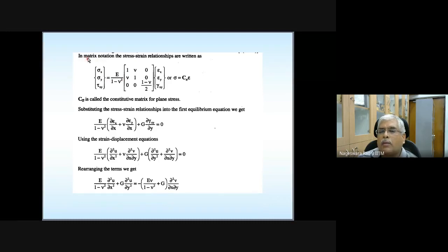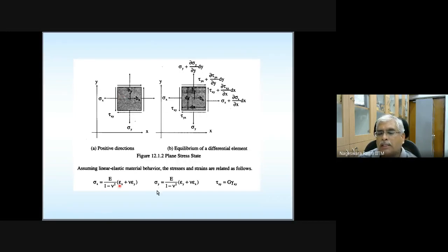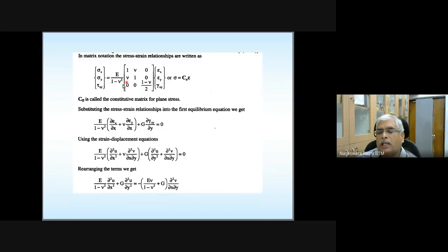These are the stress components, these are the strain components, these are the stress components which are not zero, corresponding strain components, and how they are related coming from these relations. And this 3x3 constitutive relation can be compactly written like this. And this matrix is nothing but your constitutive matrix. Constitutive matrix is the matrix or the relation which connects stresses with strains.